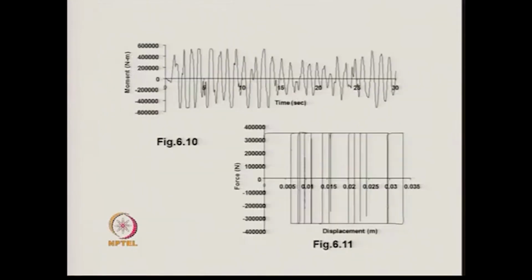So, in that particular way we perform the calculation. The final results for the two cases are shown here, that is the plot of the bending moment with time. The elastoplastic case is shown in figures 6.10 and 6.11. We see that the bending moments vary in such a way that over a small value of delta t, the values of the bending moment are almost stationary or horizontal.